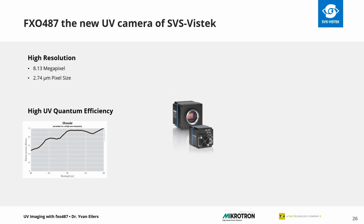You get a high resolution of 8.1 megapixel, which to our knowledge is currently the highest resolution available for a UV machine vision camera. Sony's new Pregius S technology is used to realize the pixel structure, resulting in a pixel pitch of 2.74 micrometer. We offer frame rates of 87 frames per second with 10 GigE or 1 times CXP12, and up to 194 frames per second with our high-speed 2 times CXP12 interface.